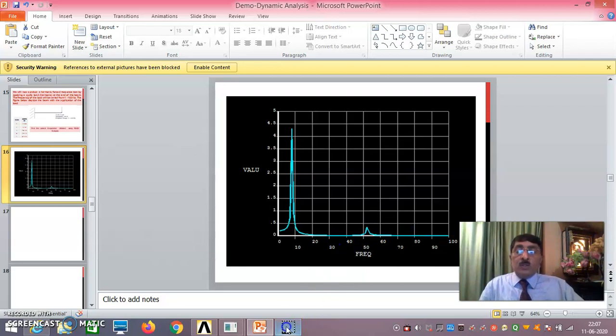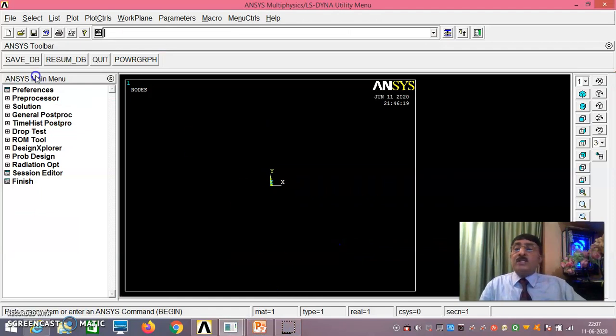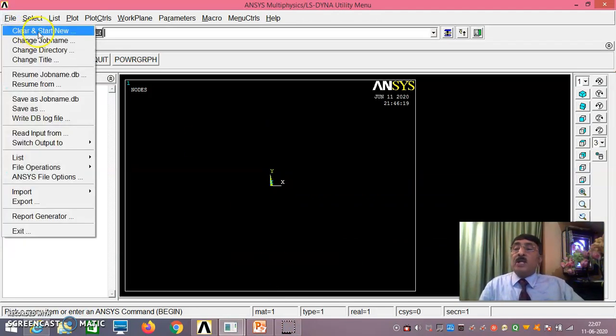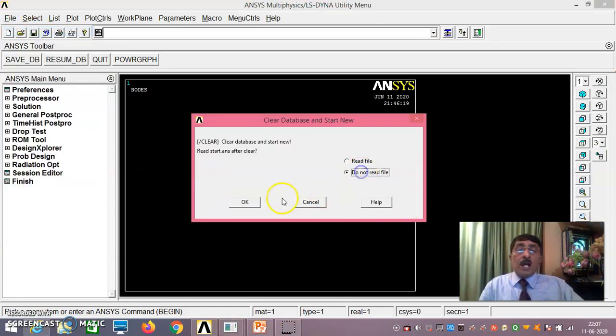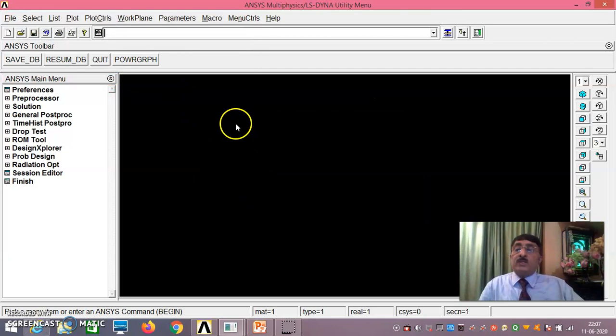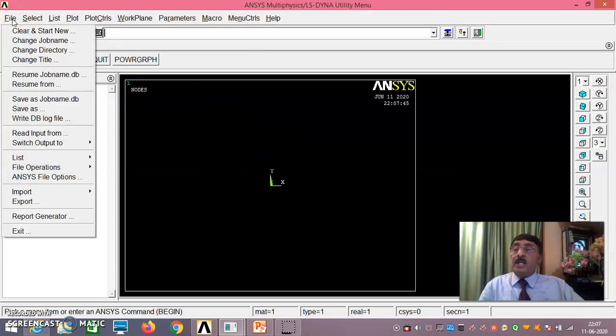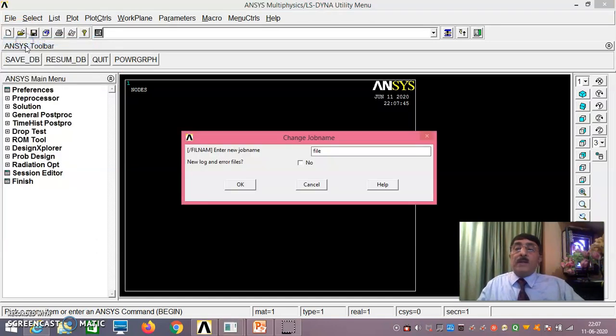Now once you know the basics, we will go for the answers. As usual, you do file, clear, start new. I'm doing it from the base, from the starting only. This you do. Then say fit. Then as usual, file, change job name.